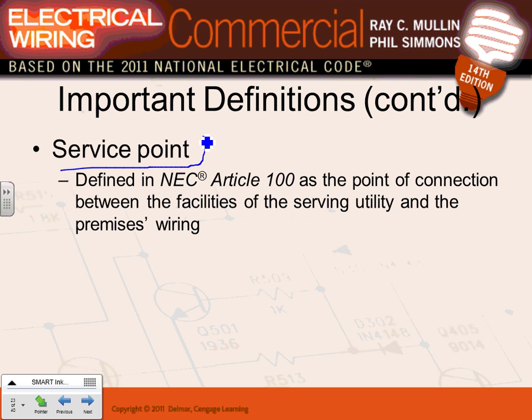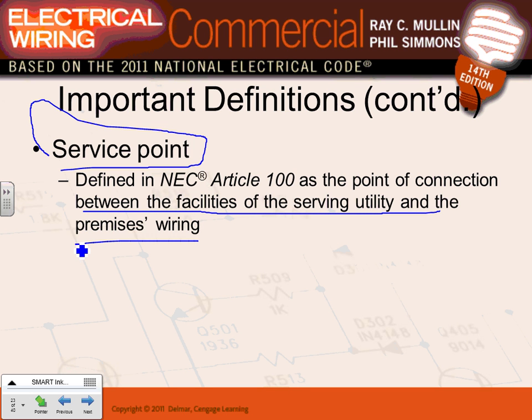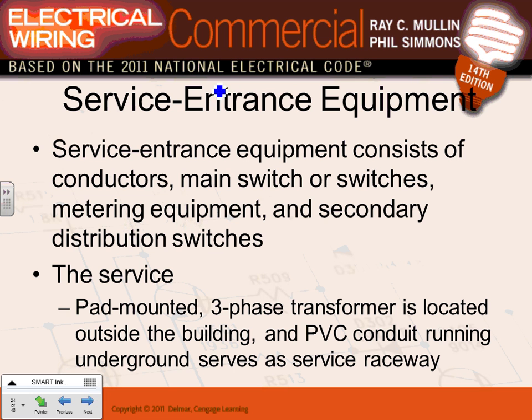Service point, the most important point, is the point of connection between the facilities of the serving utility and the premises. That's the demarcation point. It depends where. Sometimes it's the meter, pad-mounted transformer, CT cabinets, the top of the pole. Okay, so we talked about this one too. Service point, service entrance